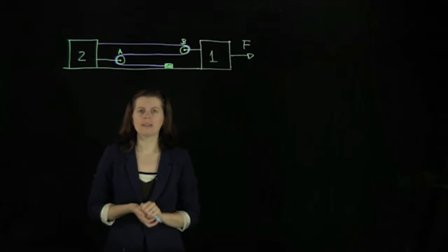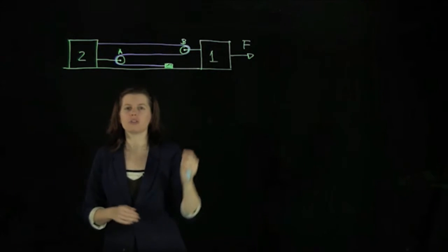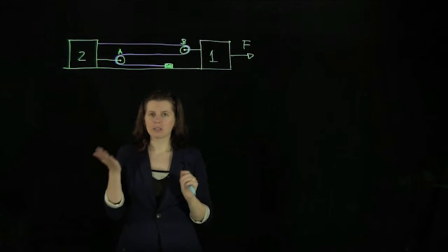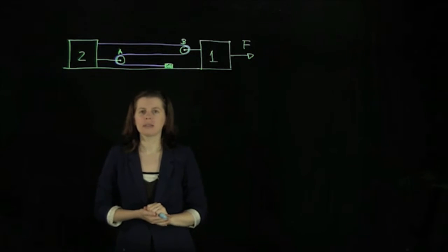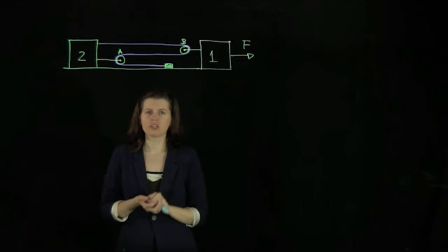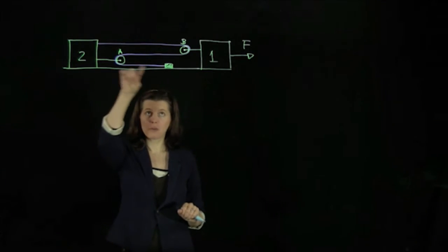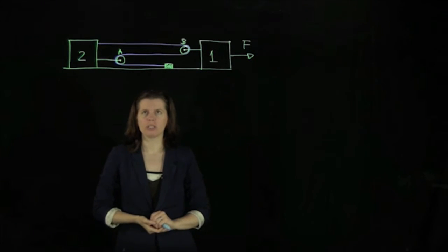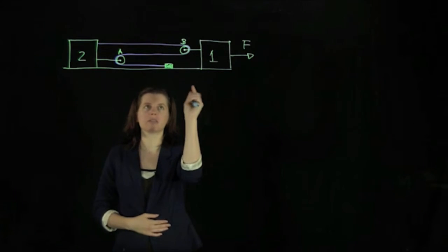How are we going to do that? Well, we have to look at this string here. First of all, it's a fixed string length, and that will help us. Ultimately, this is just a distance that connects all of these objects. And if we eventually differentiate that twice, we get to an acceleration. So the first thing we're going to do is figure out what the string length is, to then derive the acceleration condition. Let's begin by first identifying the fixed length in this problem.